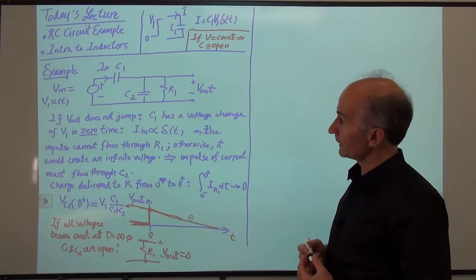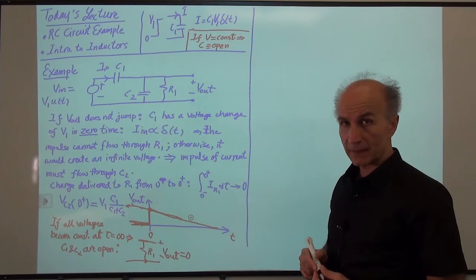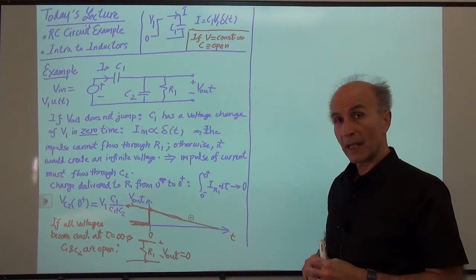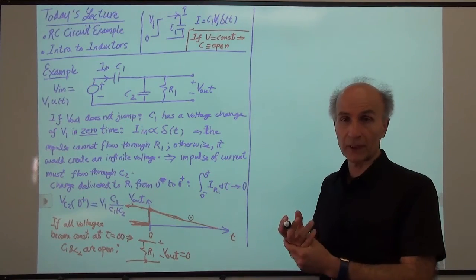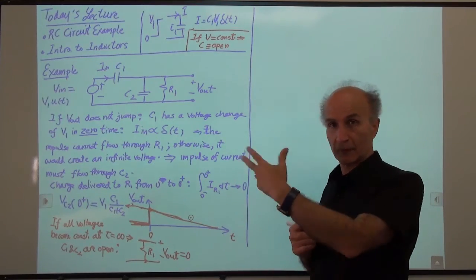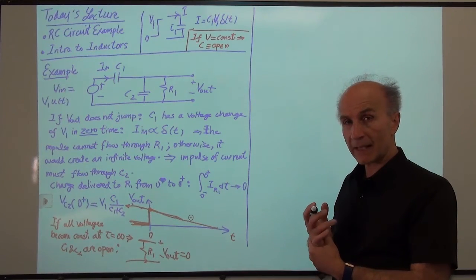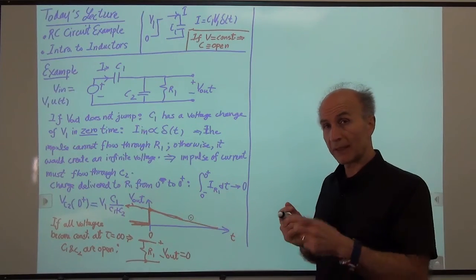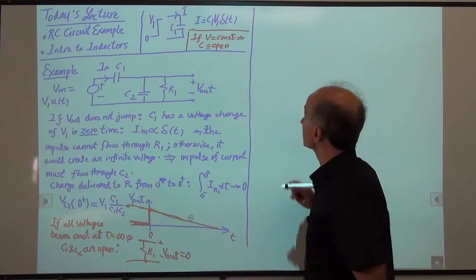Okay, can I express the output as a function of time? Yes, this is a first order system. And because it is a first order system, it still satisfies the equation I showed you last time and times before that, right? So y is equal to y infinity plus y0 minus y infinity times the exponential. So it's the same thing here. But you may ask, why is this system of first order, even though it has two capacitors in it? All right, so let's investigate that.